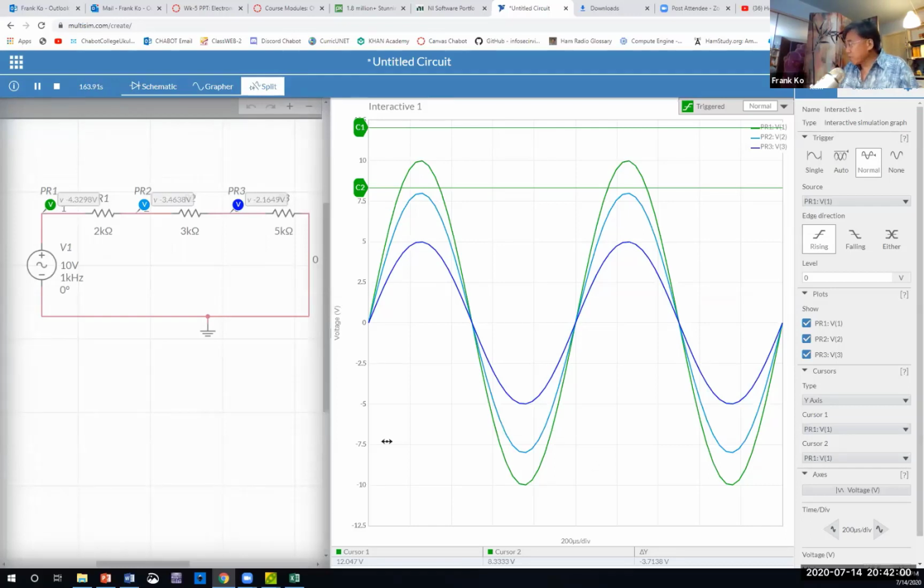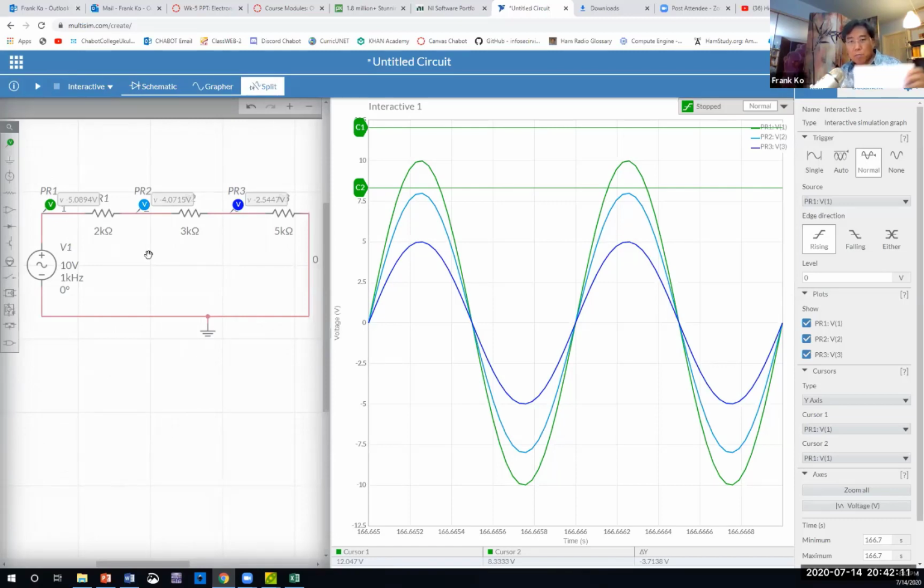So we went through this exercise together. We went through the exercise of this circuit. We did a VIR analysis of this circuit. We filled in the VIR table for this particular circuit. We had predictions for voltages across each of these. We put in test points, and from each of these test points, we have an expectation how much voltage to ground, and we were able to display a waveform that confirms those voltages to ground. Is everybody okay with this demonstration? Would you like to see one more?